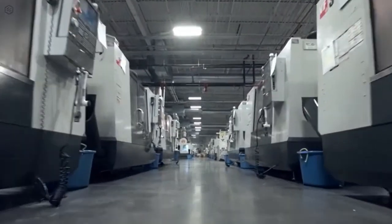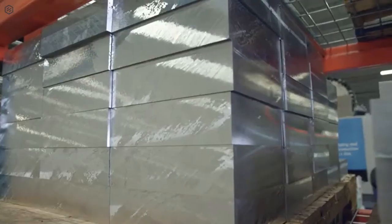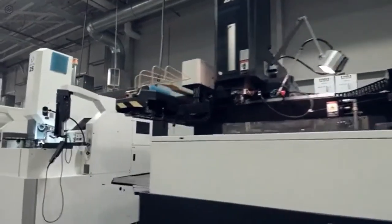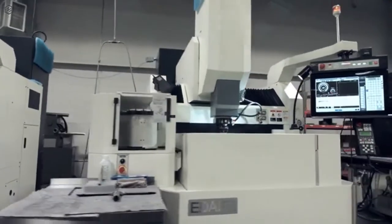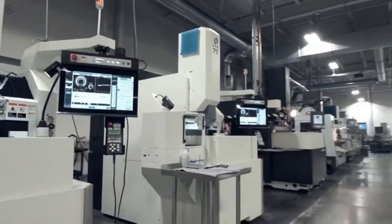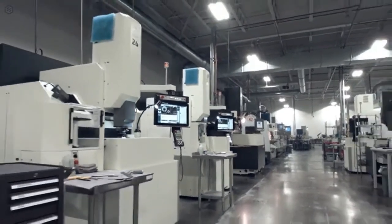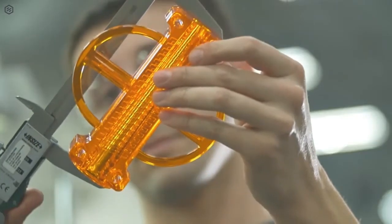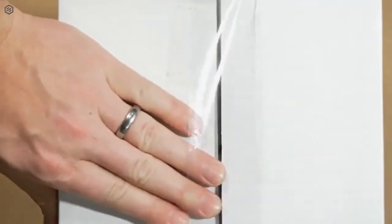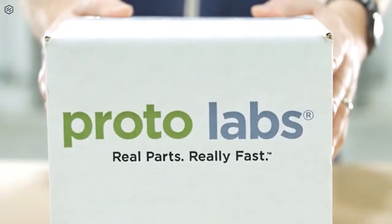The molding process begins by milling a block of metal into a mold. Typically, we fabricate molds from aluminum to reduce manufacturing time and cost. But sometimes we turn to steel, depending on the part's geometry, material, or quantity. And then, if required, the mold stops at an electrical discharge machine, or EDM machine, for a final touch-up. Whether or not EDM is necessary depends on the part geometry and other characteristics. Once machining is complete, the mold goes through the build room for hand polishing and pin placement, and then it's brought out to the press. After parts are molded, they undergo a quality inspection and are shipped out to customers. This entire process can happen within days.